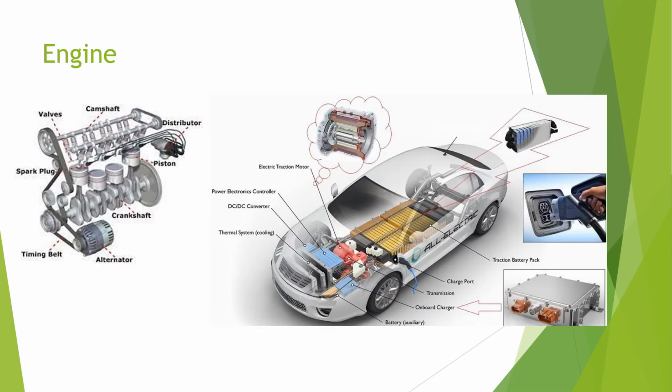Okay, so moving forward, here we have the engine. So firstly, what is an engine? It is a machine that is designed to convert one form of energy into mechanical energy. Heat engines convert heat into work via various thermodynamic processes. The internal combustion engine is the most common example of a heat engine, in which the heat from the combustion of the fuel causes rapid pressurization of the gaseous combustion products in the combustion chamber, causing them to expand because of heat, and this expansion drives the piston here. When the piston drives, it turns a crankshaft here, and this is how it's converted into movement.